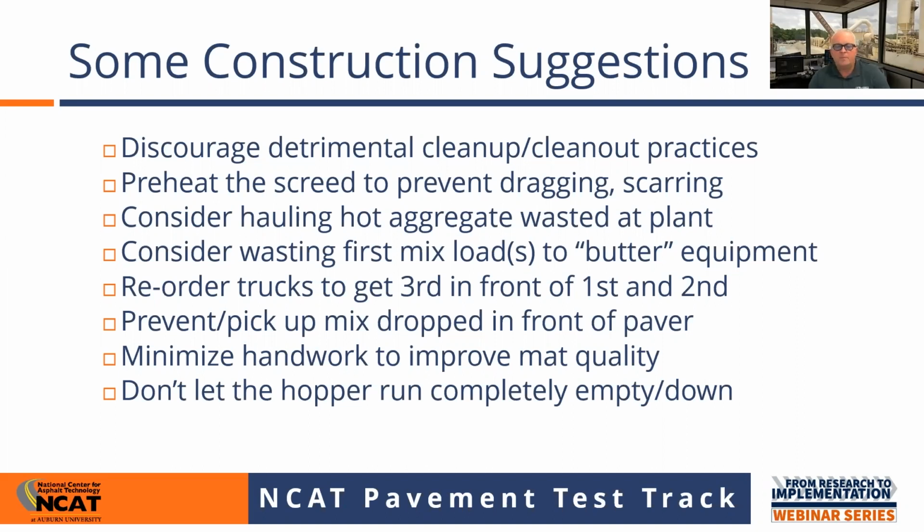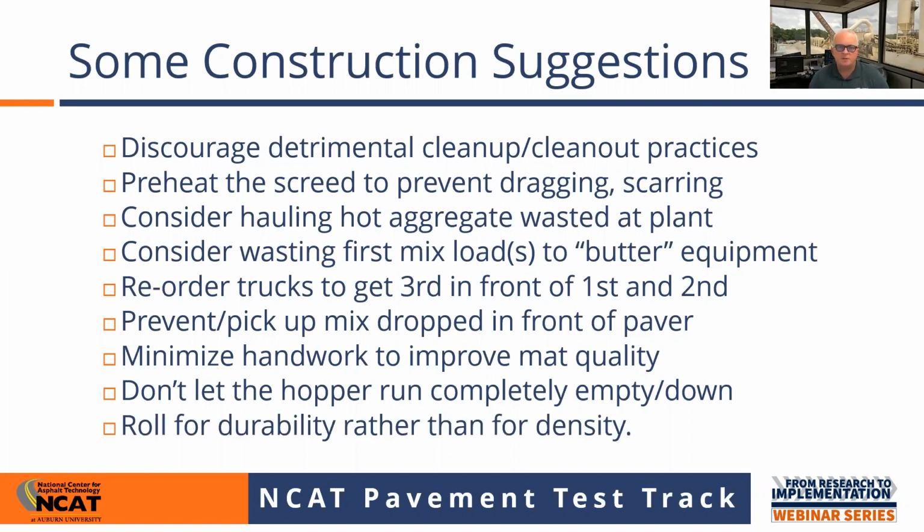Also, it helps to not let the hopper run completely down. The reason for that is because you're going to have more temperature loss when you have a smaller mix mass in the hopper. And again, this stuff is kind of a heat sink. It's open graded, so it's going to radiate heat at a pretty rapid rate. It's going to give up energy more aggressively than a dense graded mix is going to. So don't let the hopper run empty. Don't let it run down. Try to keep a good steady flow of material coming through it. On most of these jobs, we're going to be using a material transfer device like a shuttle buggy, and that should help us to maintain that mass of material in the hopper insert or in the hopper.